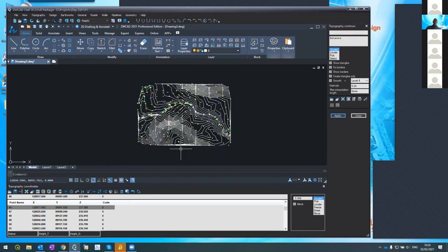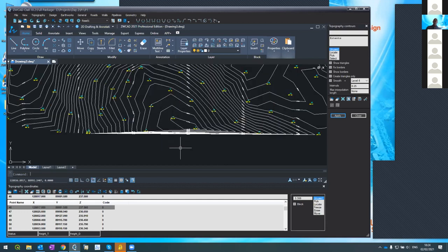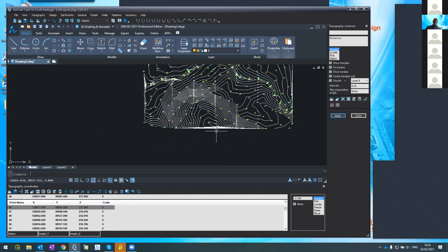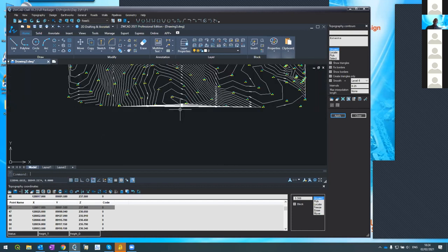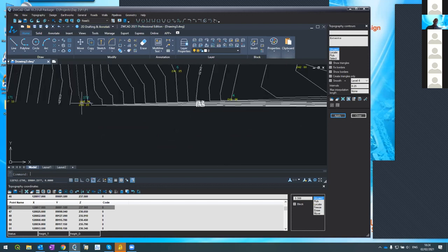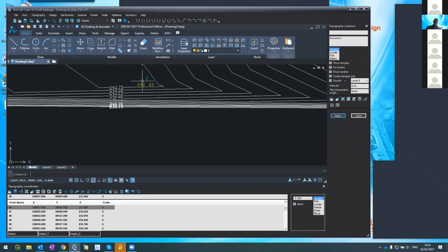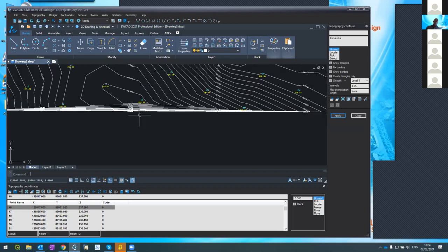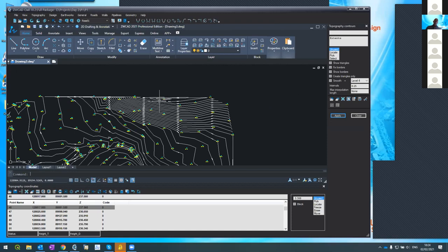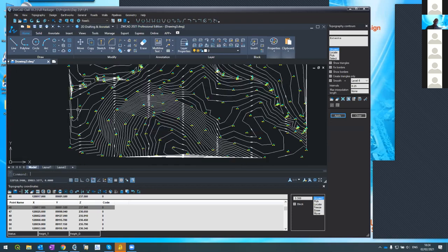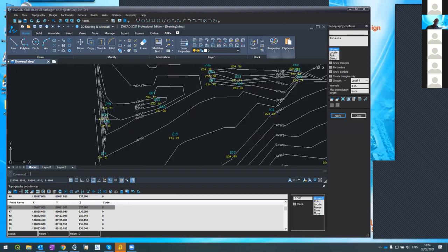Usually we see it in roads, in longitudinal profiles, but here you see all these contours? All these contours usually come because of an interpolation between this point and this point, and the points on the top. Now, it might be that there's a hill here, but we are not sure. Usually, it's not realistic. Also here, the software doesn't know how to end the survey here.